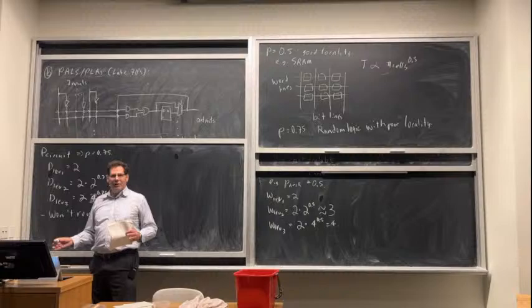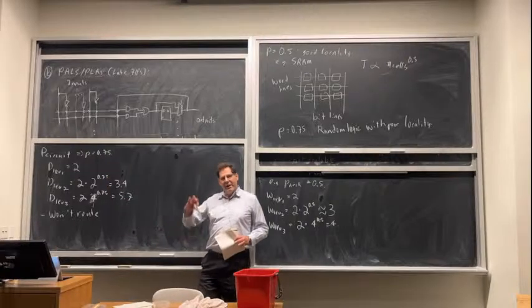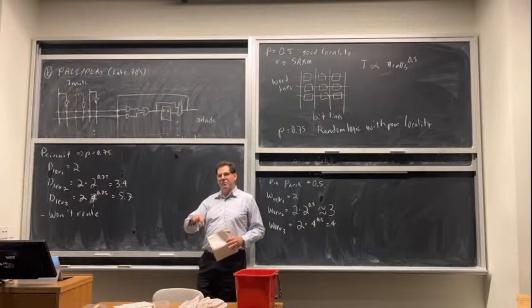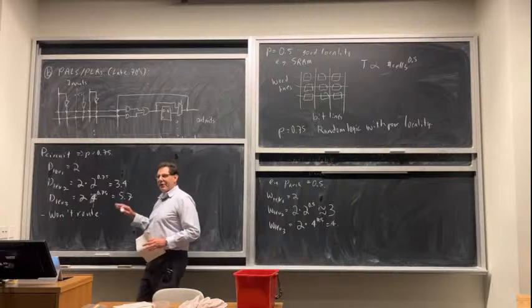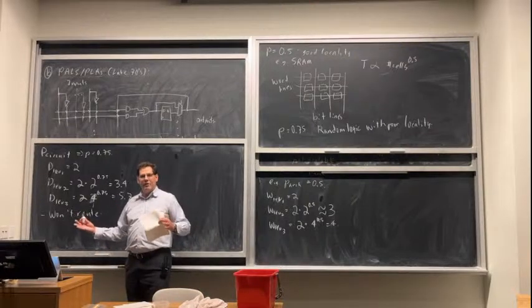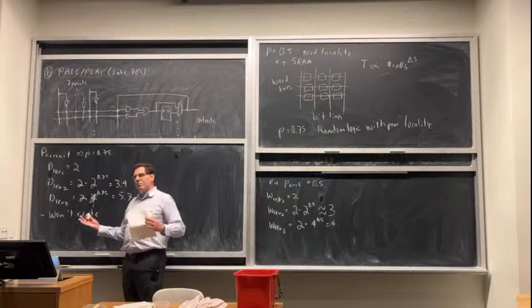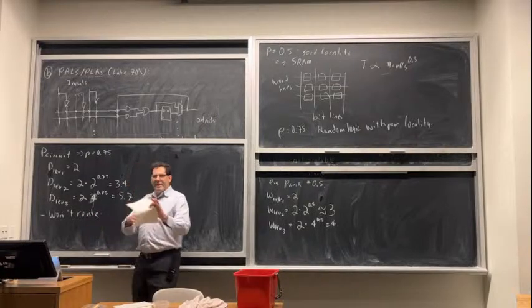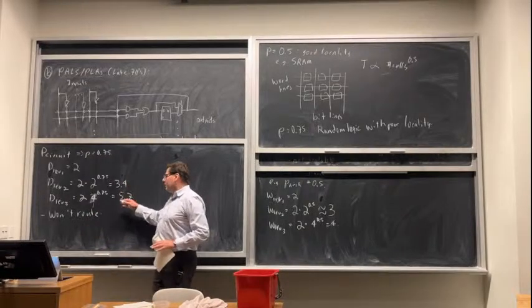But if most people are okay, they had rent exponents of 0.5 and they were doing fine, then I'd probably rather not do that because widening my channels increases the cost of the chip. So there is a problem with doing that if only a few people need it. So let's say I'm in that case. I actually think most people don't need the channels to be this wide, but this customer does. Is there anything I can do?